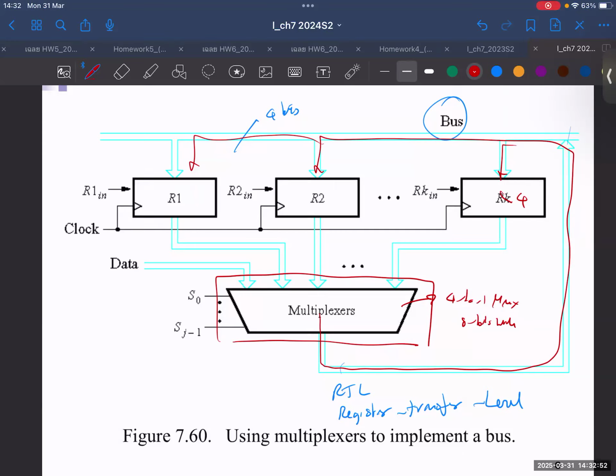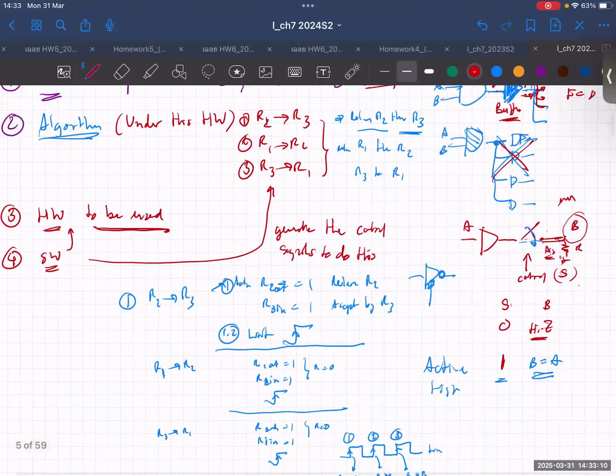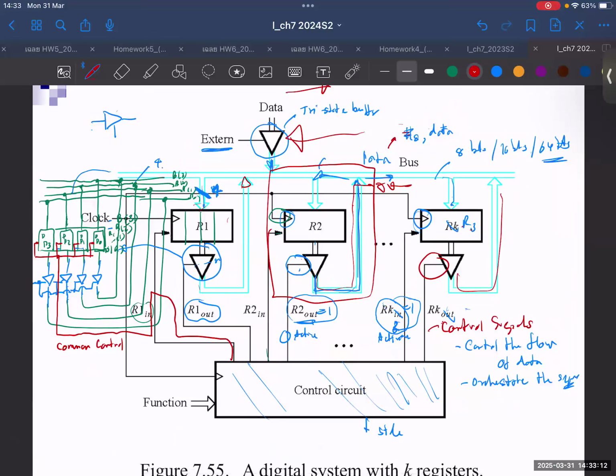The mux is huge. This is a gate. Remember that? How are you going to design the mux? A 2-to-1 mux, how many gates do you need? You need 4 gates at least for the mux. So in terms of hardware, this architecture is much smaller, because it's just a gate, like just a buffer, which is quite small compared with a mux.